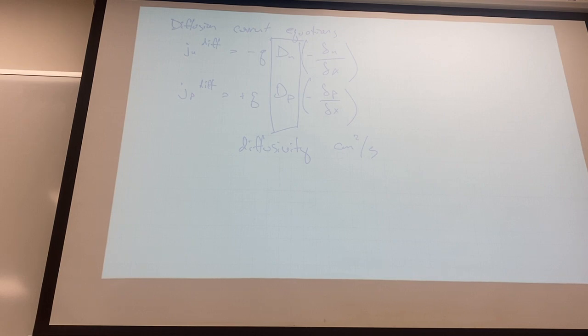That constant is, either substitute the n or the p as you need, because on the other side is mobility of n or p, depending on which one you're talking about, times Boltzmann's constant again, temperature, and the electronic charge. So it's the mobility times this thing that we're going to be talking about a lot. This we abbreviate as V capital T. This is the thermal voltage.